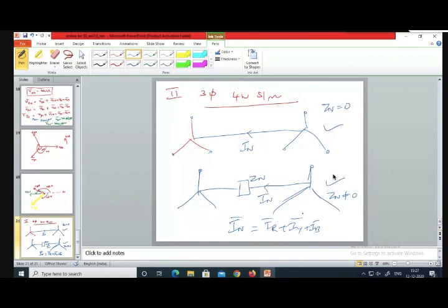So the start point of the load and the supply system will get connected and will be at the same potential. Then it is called shorted. So then neutral impedance is 0 here in the first case. So here this point and this point is shorted.